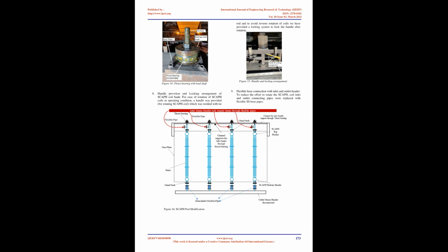Based on this concept we chalked out the in-house methodology of erection, and it was a challenge for us to carry on with this modification at the lowest possible cost. Static SCAPH was thus modified into a rotary SCAPH, just like an operating butterfly valve, which can be rotated by 90 degrees after the unit achieves full load or when its requirement ceases. Man, machine, and material were expedited, and a step-by-step erection procedure has been explained in this paper.